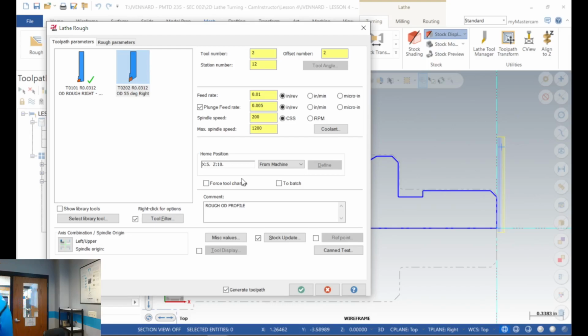I'm going to give you guys a quiz next Thursday. I'm going to give you a sheet and say, here are the parameters I want you to use for the tool. Use the default tools, but here are your cut speeds, here's your roughing feed per rev, here's your finish feed per rev. Plug all these in correctly. That's some of the stuff I'm going to check for. All right. So we're going to call this a re-rough because that's really what we're doing. We're coming in and re-roughing.